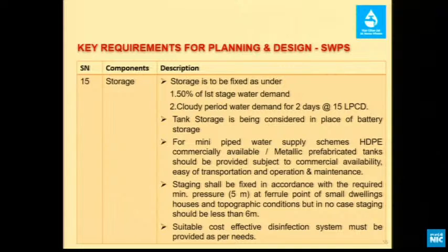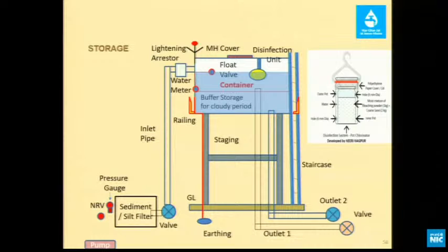So storage, as here only already Rana said that 50% is taken. Here I have to add one thing. For the cloudy period condition, maybe 30-35 days, I have a buffer storage, minimum for 2 days at 15 LPCD per day. Next. So this is an example. I have shown the buffer storage and more storage.